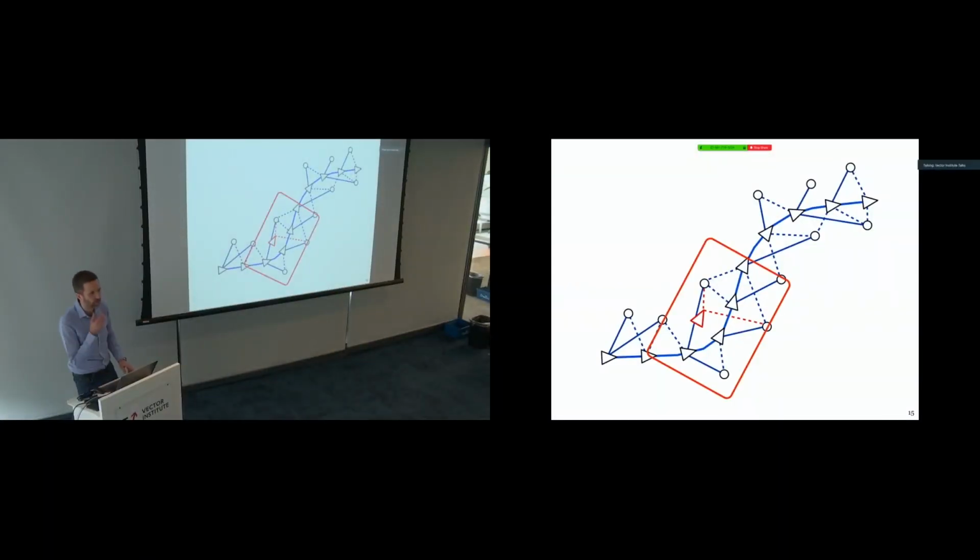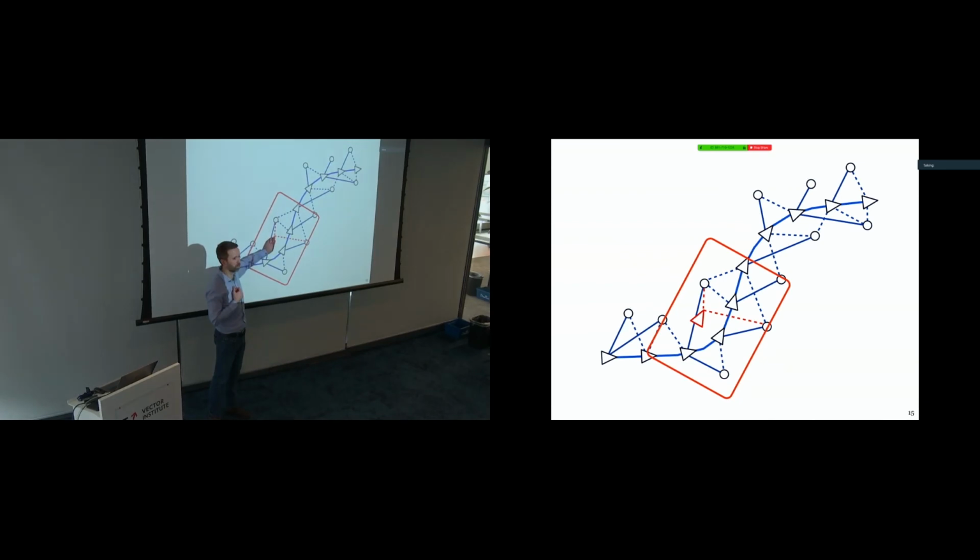Right, so when we're localizing, we're not really just trying to directly learn the command to the robot. We actually solve for the 6-degree of freedom pose of the live view of the camera against the map. And then we use, say, model predictive control to try to zero that error. So the controller is designed to work with the robot being anywhere with respect to the path.